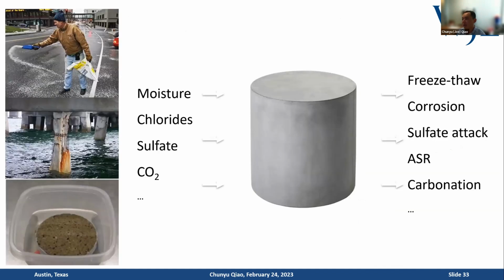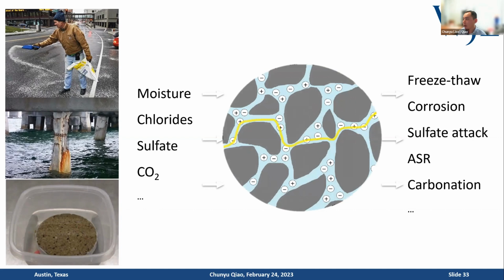So that being said, if we have different porosity, different pore tortuosity, those kinds of different features of pore networks, the electrical conductivity can be different, because it will go through a more tortuous or less tortuous path in a higher porosity or lower porosity. That will give a different concrete bulk resistivity. So the pore network is really important for durability issues because almost all the external substances are the root causes for all kinds of concrete durability issues.